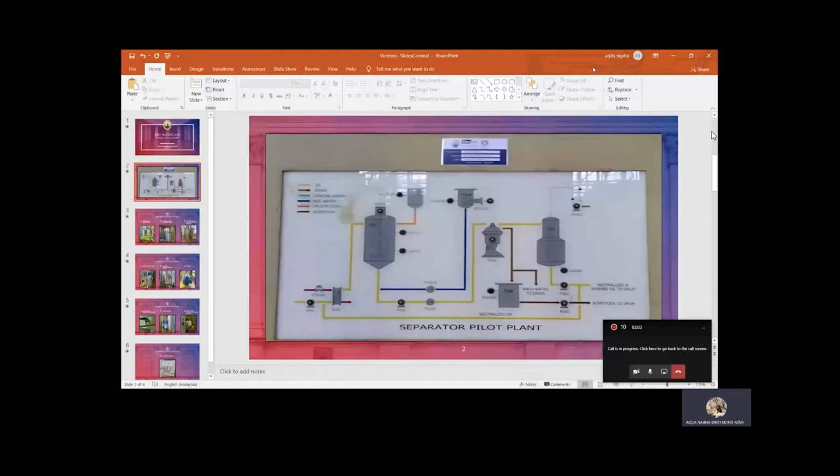Crude oil in the drum and caustic soda will flow into a neutralizer washing tank and will be mixed by the agitator. After a period of time, the mixture will be released from the tank and will flow into the separator reactor. The mixture is processed simultaneously with hot water to make sure the oil does not get stuck in the pipeline. In the separator, the oil mixture is spun at 3000 rpm to segregate the soap stock from the oil.